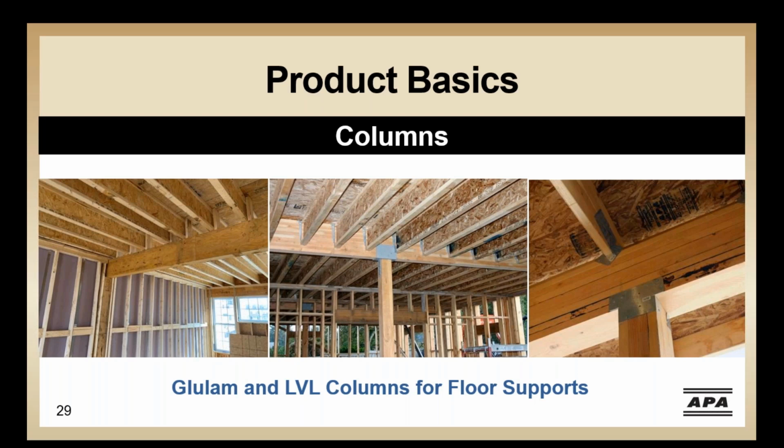These columns can be useful in the basement or any of the upper floor stories when compatibility and workability are important to the framer. Stock glulam columns are available in multiple sizes ranging from 3 1/8 to 8 3/4, including the common construction sizes of 3.5 and 5.5 to match other lumber framing materials. SCL columns are typically available in 3.5, 5 1/4, and 7-inch widths.